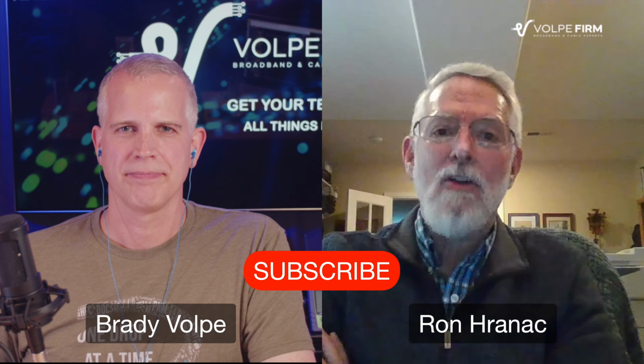But hopefully, attendees and viewers have taken away from this presentation that there's a lot of math involved in carrier to noise ratio, and an understanding of it can help you appreciate the importance of being able to calculate the CNR. If you're out doing troubleshooting or maintenance, you can say, all right, for this 5 amp cascade after the node, the calculation says this number, and what am I measuring? If I'm within a dB or two of that, things are probably pretty good. If you're 5-6 dB off, you better go back and find out what's going on.